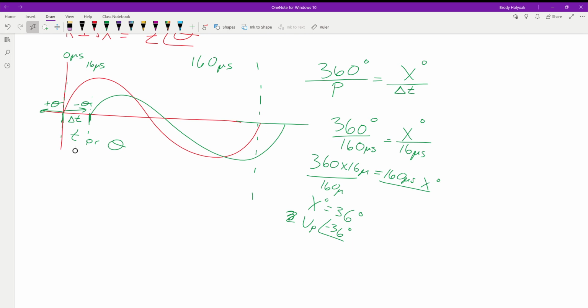Yep. And so it's going to be from the same spots, because this waveform could be clear down here. So we want to go from when it crosses the x-axis as it's going positive. That's where I like to take my measurements. You can take it from here when it's going down and crosses the x-axis from the positive. It doesn't matter as long as you're doing the same thing to both sides. I just like going from where it crosses the x-axis going positive.